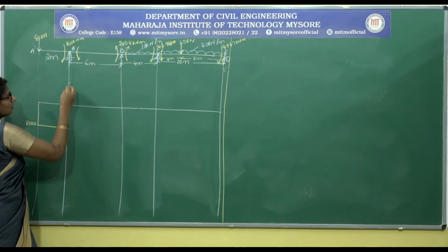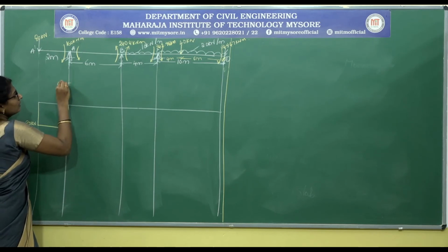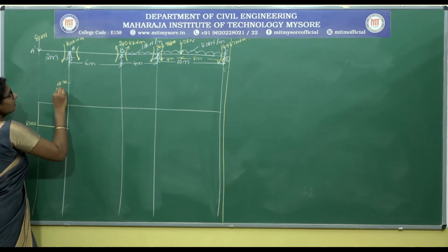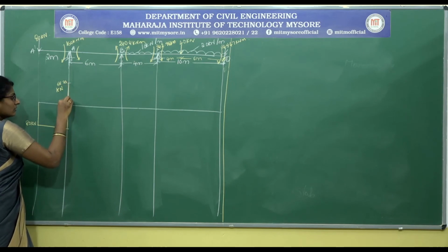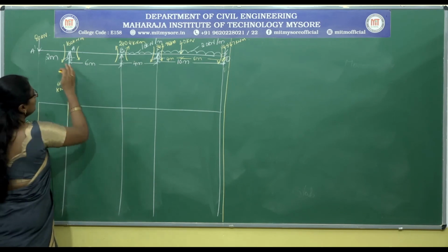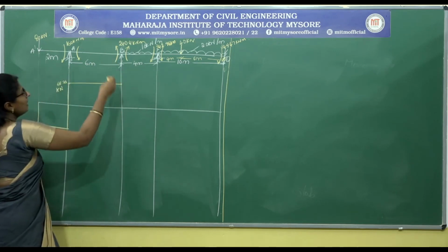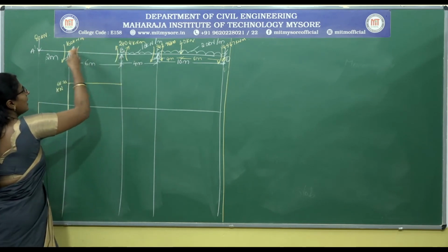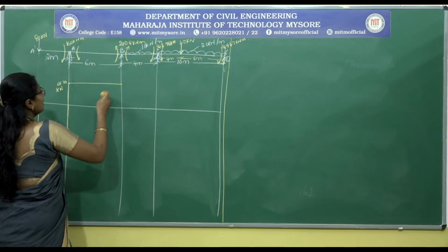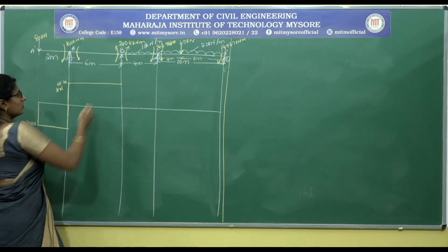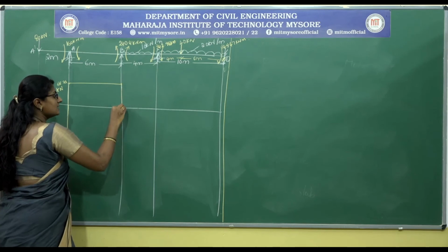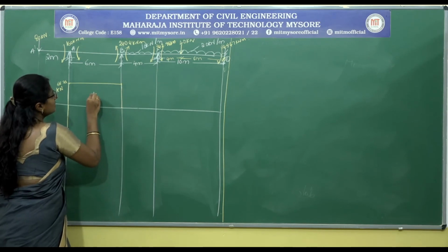So plus 66.73 comes somewhere here, 66.73 kilonewton. So join this. Then in between A and B there is no load acting, so I take it as constant. At B, for span BA, that is RBA, is given by minus 66.73. So plus 66.73 minus 66.73 will be 0.